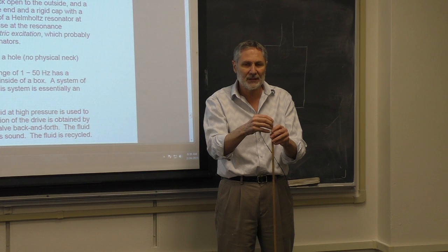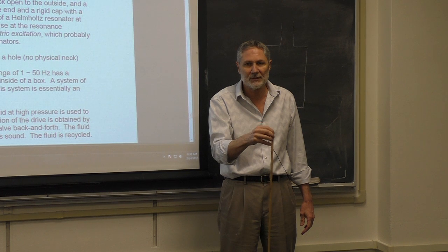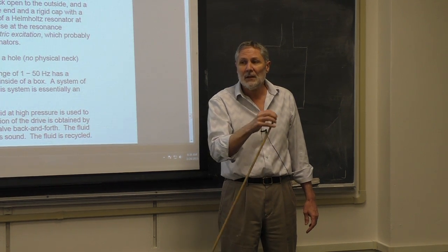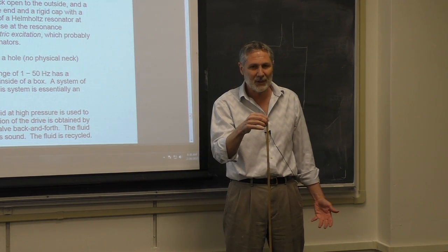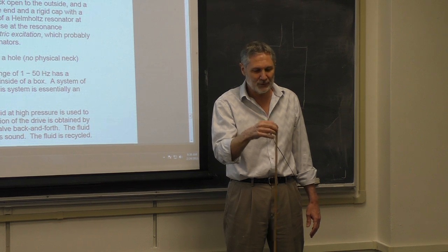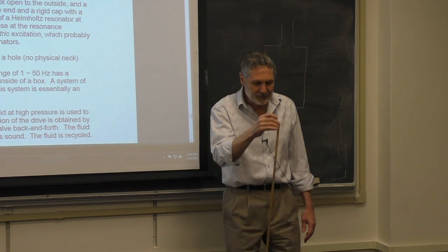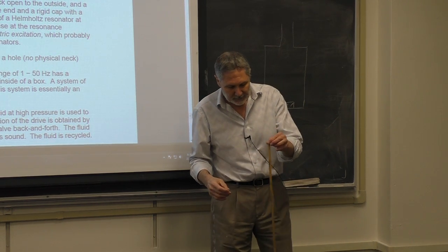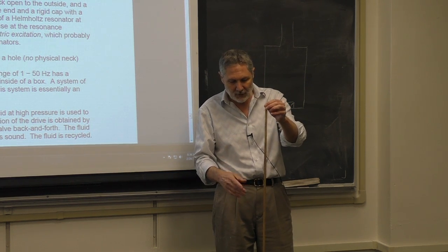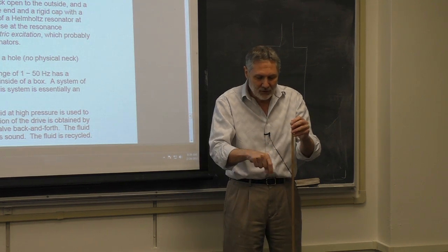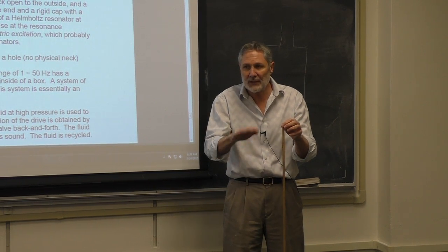This kind of excitation has completely different properties than the direct excitation. It's called parametric excitation. Anyone ever heard of it before? It's in our nonlinear course, because our nonlinear course has nonlinear oscillation waves. I have a whole chapter on this because I have expertise in this area. So what's happening here is that in this frame of reference going up and down, the effective gravitational field is being modulated compared to the Earth.